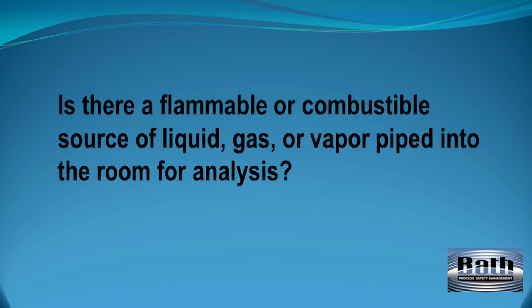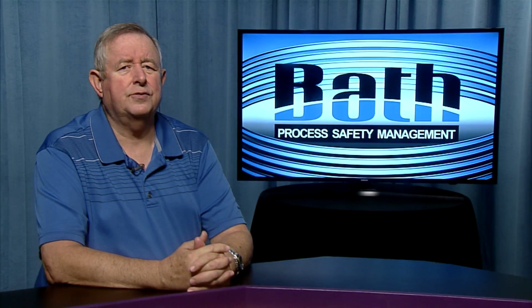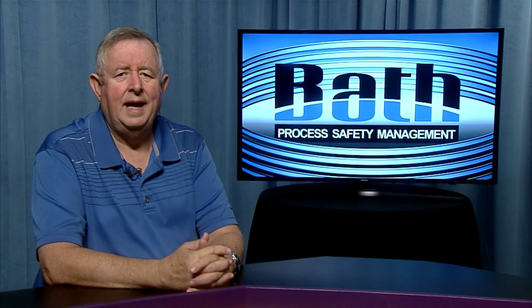You must first determine if there is a flammable or combustible liquid, gas, or vapor being piped into the room or building for analysis. If there is no flammable material introduced into the building, then specific API RP 500 analyzer room or building guidelines are not applied in determining the building's interior's hazardous area classification. You must now consider the interior of the building as having electrical equipment only and classify it accordingly.